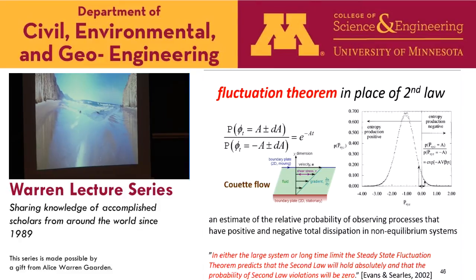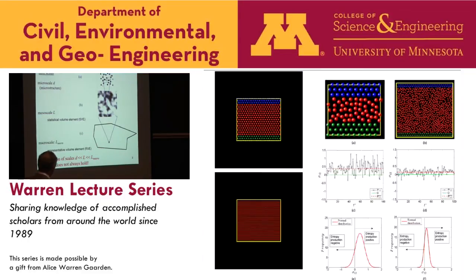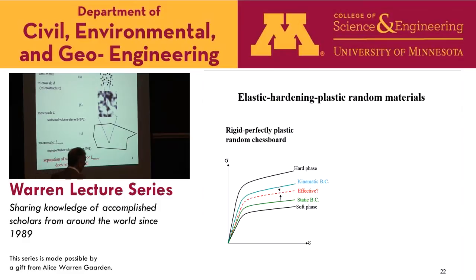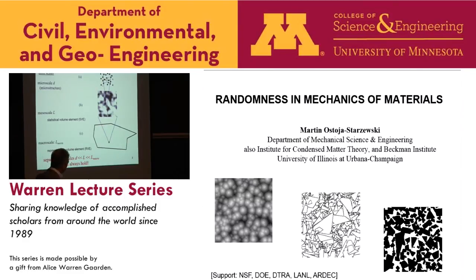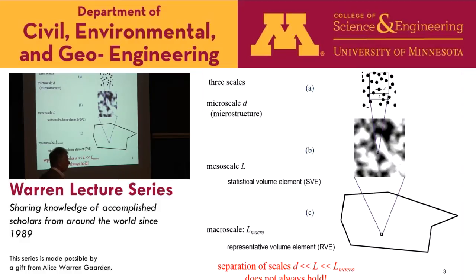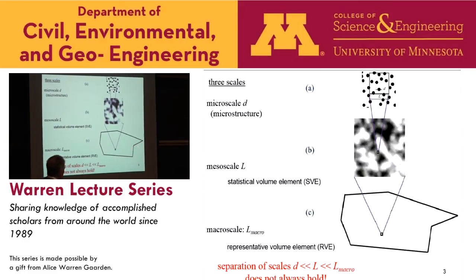All right, so my answer is, if I do a problem without body forces, so no elastodynamics, because elastodynamics puts in another wrinkle, the wavelength, so we can discuss later. But if I do a static problem, effective moduli would be good, providing I don't have any very sharp corners or geometries like that, because locally I would really have to look at those particular geometric effects.